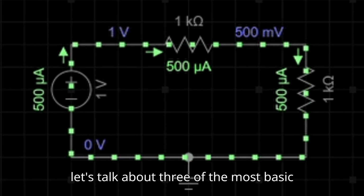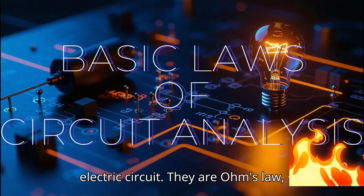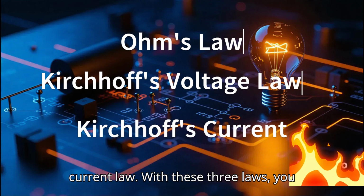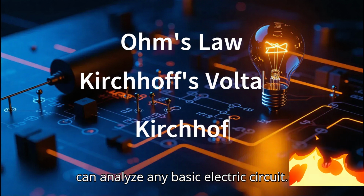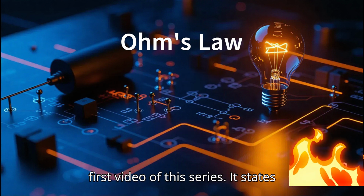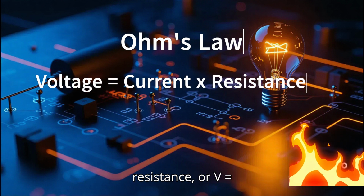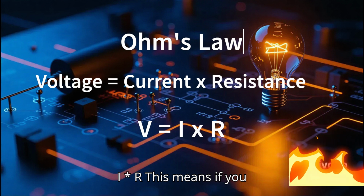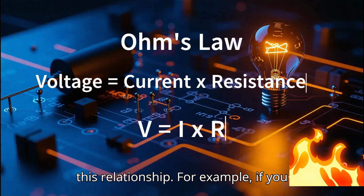Now, let's talk about three of the most basic laws that are used when analyzing an electric circuit. They are Ohm's law, Kirchhoff's voltage law, and Kirchhoff's current law. With these three laws, you can analyze any basic electric circuit. Ohm's law was already alluded to in the first video of this series. It states that voltage equals current times resistance, or V equals I times R. This means if you know two of the electrical quantities, you can easily determine the third using this relationship.